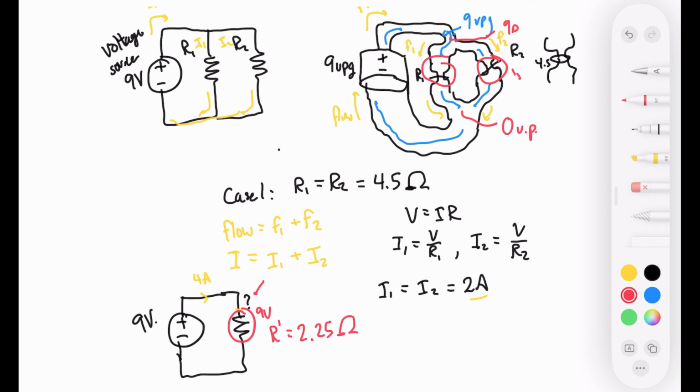So it's always better. Now, one analogy you can think of is traffic. It's always better to have 2 lanes than 1 lane, even if one lane is really, really slow. If the other one is really fast, you're still going to get some marginal benefit of having 2 lanes because the cars are going to try to distribute. They're always going to try to pick the shortest lane. And similarly, even if one of these resistors is really high, we should expect the overall resistance of the combined parallel series to be always less than the individual ones. And likewise, when they're in series, you should always expect the sum of those to be larger than any of the individual ones. So that's one particular sanity check.